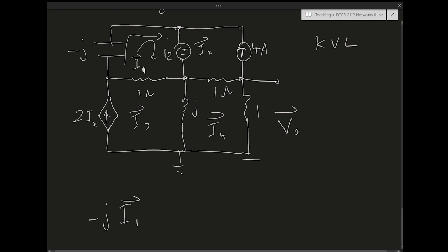And then this is easy. I have a voltage source in the loop. I'm going to meet the plus of the voltage source first when I go clockwise, so I'm going to have plus 12. And then I'm going to have plus I1 minus I3. In this branch, the current flowing is I1 minus I3. There are two loops passing on this branch, the I1 loop and the I3 loop.